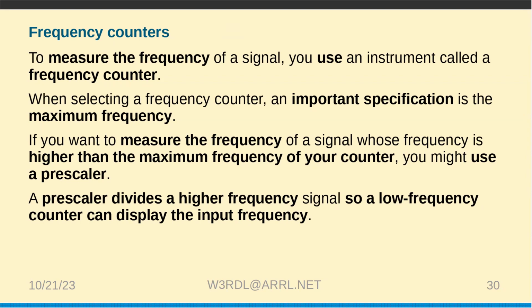They may have improved it on the newer models, but it's limited to doing 102 points. So the wider the frequency band you want to look at, the less accurate it is because you get a fixed number of samples. If you really want a good reading, you look at a narrow range and then change it to a different range.